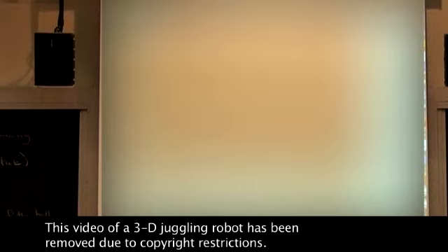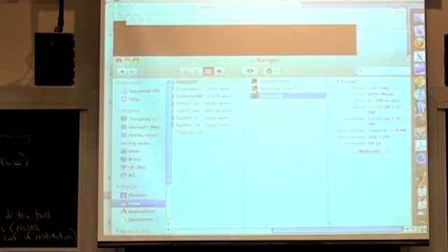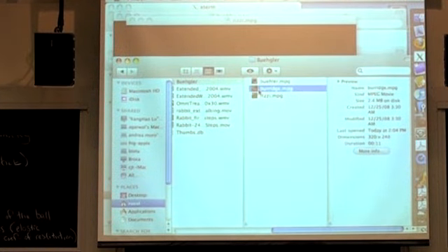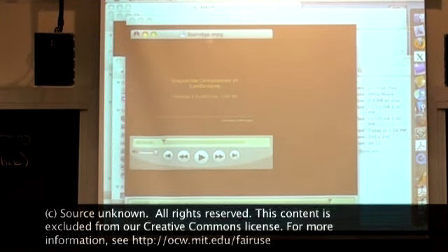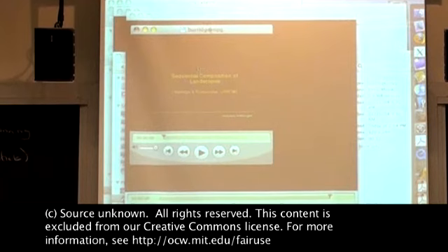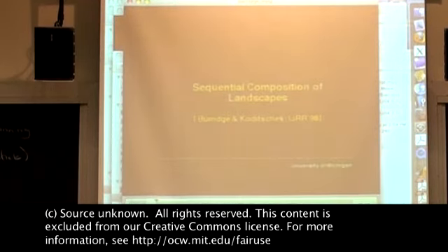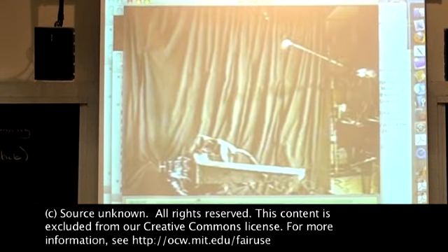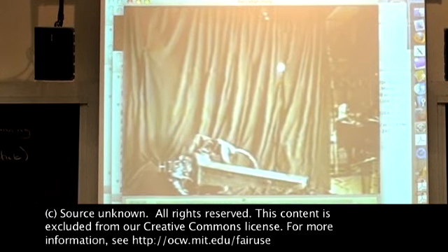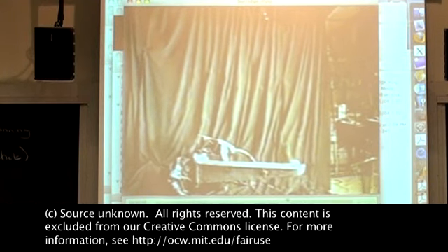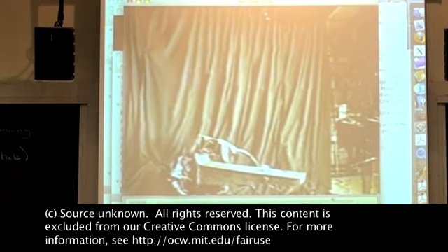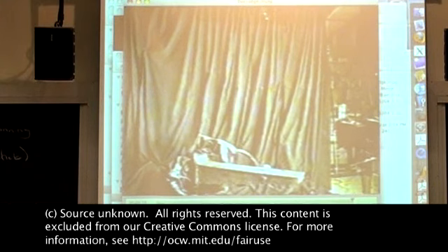And then they got so good that they started doing other maneuvers like catching and palming and things like this. It's actually turned out to be pretty much the same control derivation. They just set the desired energy to zero, and suddenly they have a catching controller. And then this is palming when they're doing their thing, okay? And then they can get it back up to bouncing with the same sort of energy shaping.